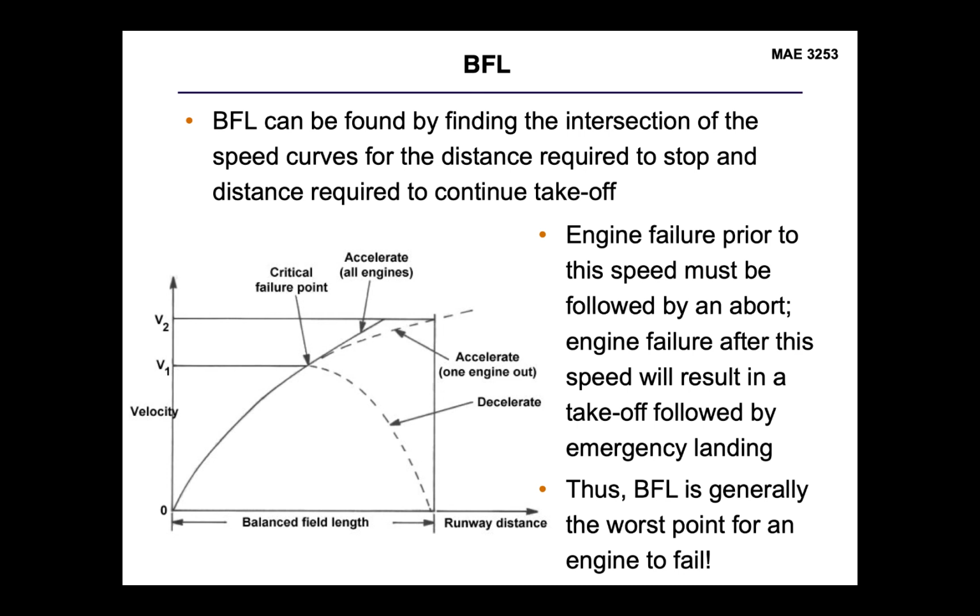So we can typically think of this balanced field length portion or this critical failure point as the worst case scenario. If we happen to have an engine fail at that critical failure point, that's going to be our maximum possible runway length that our aircraft would utilize.